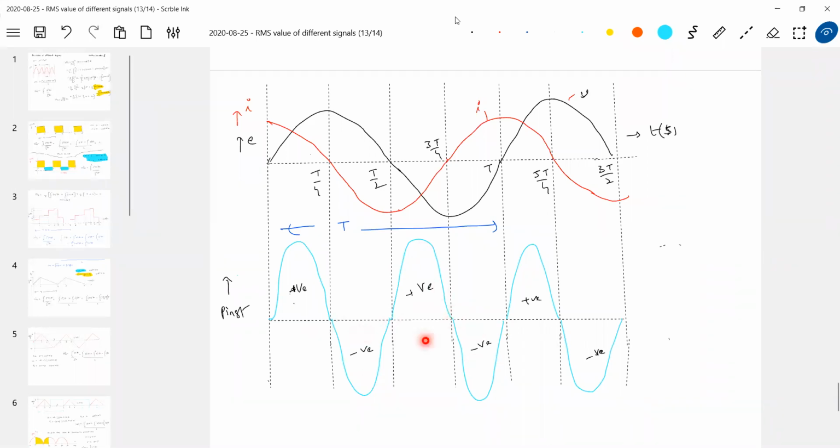So what is the net power dissipated? Zero, no? So therefore, what is the capacitor? It will not consume power. It will not dissipate power, better say. It's an energy storing element. There's exchange of energy between the source and the capacitor. And twice that exchange occurs: first it will draw the energy and return back, again it draws, again it returns back.